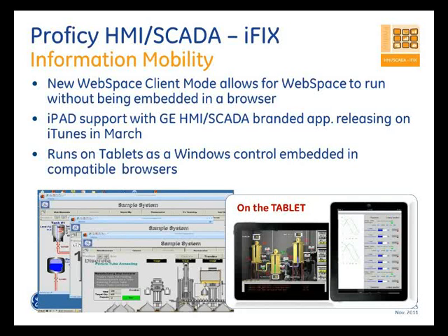Again, WebSpace with iFix 5.5 only supports Windows 7 64-bit on the server side. As far as 2008 is concerned, you can use 32 or 64. But from a Windows 7 perspective, the server side only supports running on a 64-bit OS. On the client side, you can have a 32-bit or a 64-bit OS that you run Windows 7 on, but from a server standpoint, you have to have the server on a 64-bit OS.